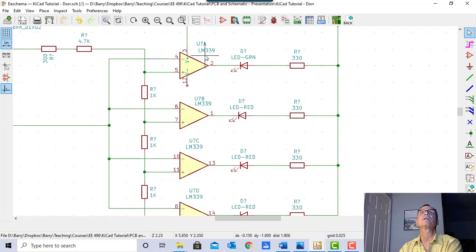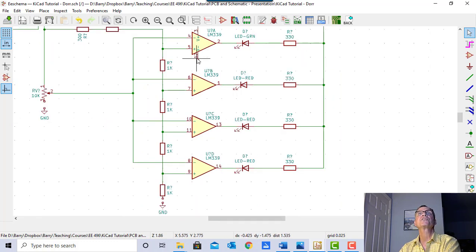Let's kind of put them all in the same place because that way, when you look at these components on the schematic, oops, move that, their reference designator and component types will be kind of in the same place, and that just makes it easier to read. Like that. There, that looks nice. And see, now I have a clean place to put my ground.